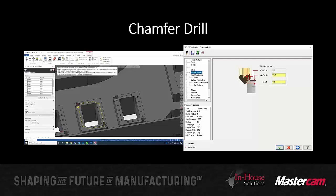What the chamfer drill toolpath is doing is taking the effort out of chamfering multiple holes at once for you, where the only real parameter to enter, as you can see here, is the depth or width, your choice, of the chamfer that you want to add in, and how long you want to dwell. It's going to take the size of that cutter and the flat on the tool that you've selected. If it's a true chamfer mill or a spot drill, there won't be much of a flat. There'll still be a tiny little land. But relative to those flats, it'll automatically determine how deep to go for each hole.